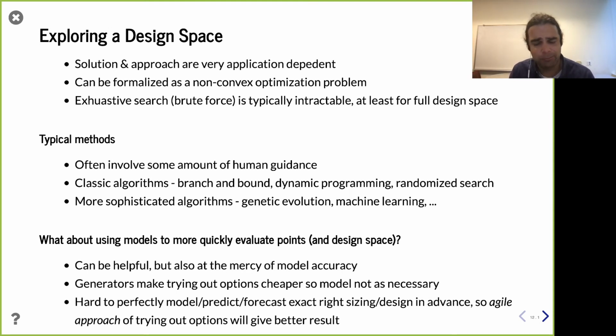And that kind of flexibility is really easy to do with Chisel. You can be a little bit more aggressive rather than just changing a buffer size or something like that. You can change something more significantly because it's not hard to do, right? In Verilog, changing buffer size, yeah, you can do that easily. But to change something much more dramatically with architecture or topology, it's going to be a lot of coding, but perhaps not with generators, right? That's kind of the goal.